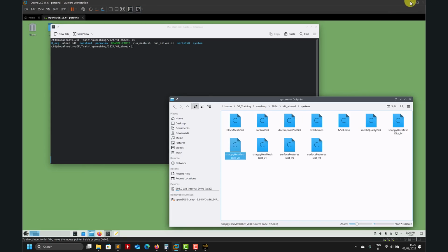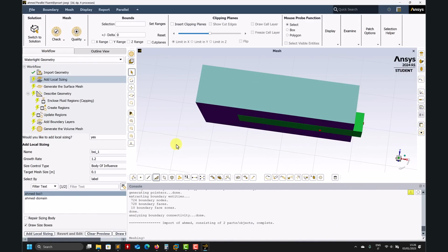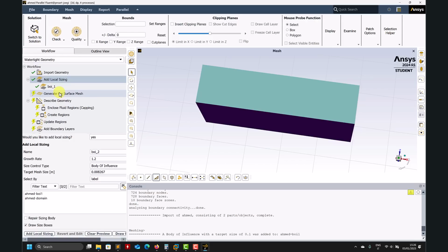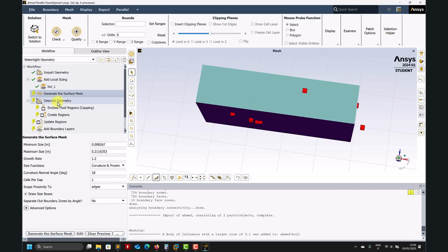So yeah, if I use 4, I will be out of that 1 million. So let's use these values, 0.1, so twice those, to avoid the license problem. So there you go, I add that local sizing. You can add some other sizing. For the moment, I will leave it like that. And see here that I go 0.2, so I'm doing that half.